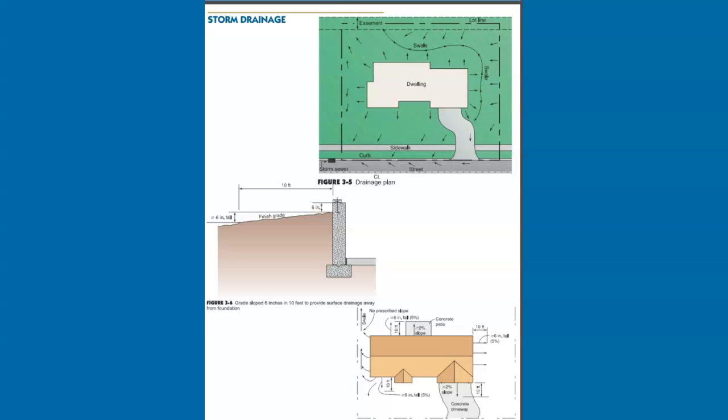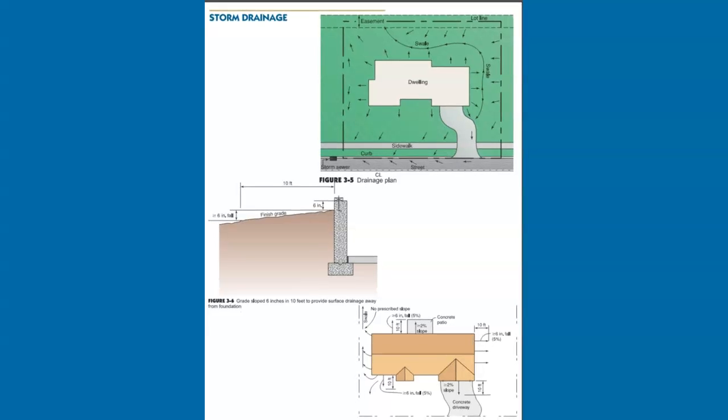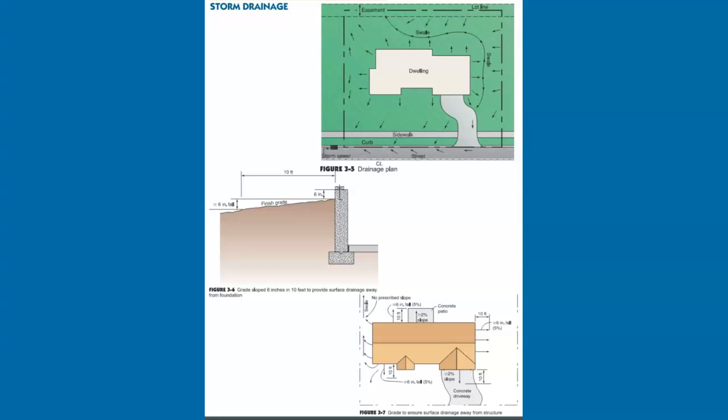Water held against the foundation leads to wet or damp basements or crawl spaces and over time can cause damage to construction materials both inside and outside the structure. Mold thrives in such moist environments, contributing to an unhealthy living environment. In addition, water saturation of the soils adjacent to foundations increases the lateral pressure against the structure. Proper design of surface drainage also prevents nuisance ponding on the lot and possible flooding of structures during periods of heavy rain. The IRC lends some discretion to the building official in determining alternate methods for adequate drainage.